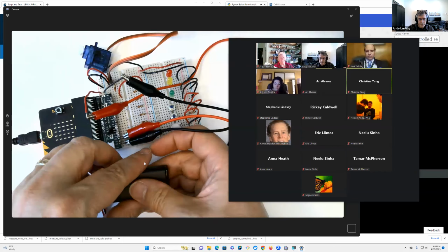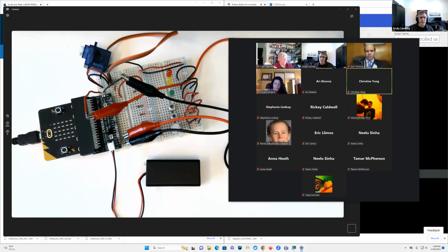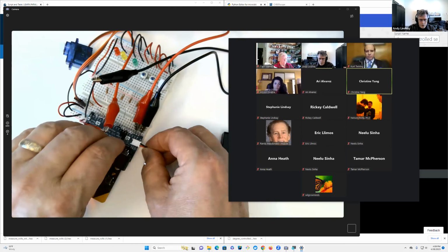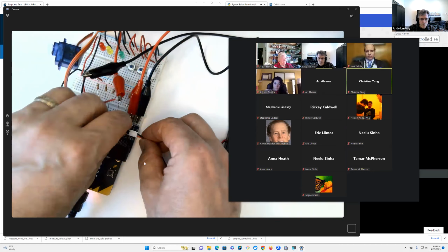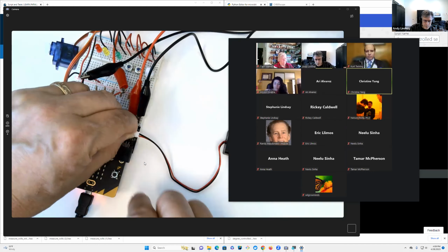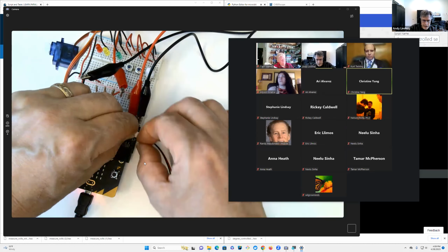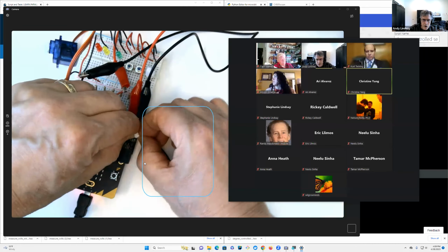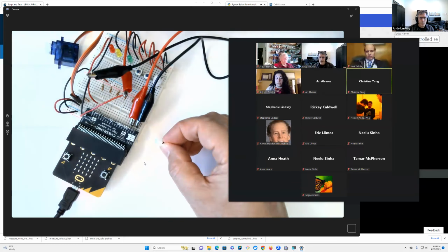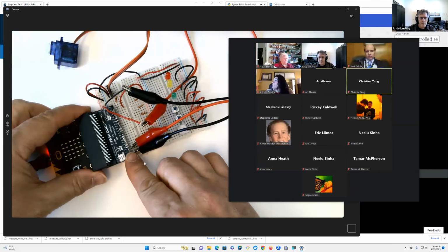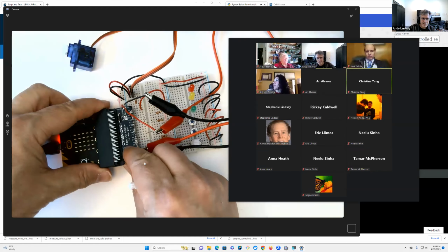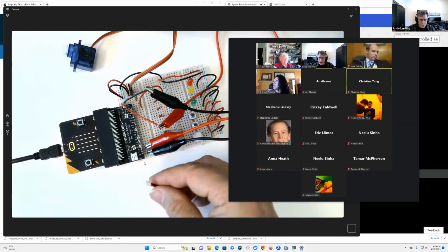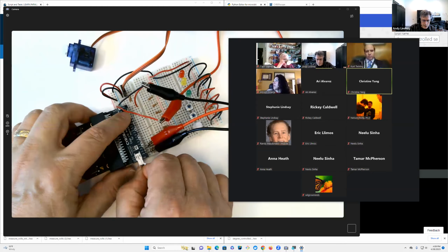It's an open circuit. Now, for those of you who really do need to get the plug out for whatever reason, the most important thing is you want to hold on to the socket and then grab the little wings that are sticking out of the plug, and then just kind of start wiggling back and forth, and it will come out. But you might notice I actually bent the socket a little bit when I did that. And it's okay to just bend it back. It should be fine.